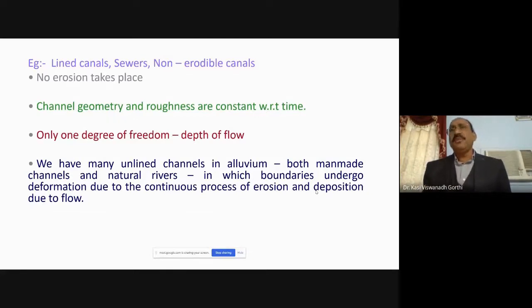Where do they flow? They flow as long as the velocity is maintained. At some section, after flowing for about say 100 kilometers also, if the velocity is reduced there because of the longitudinal slope constraints, slowly these soil particles will have a tendency to settle down. The place where the soil particle is removed from the section is called erosion. Where the soil particle is getting deposited, settling there, is called deposition.